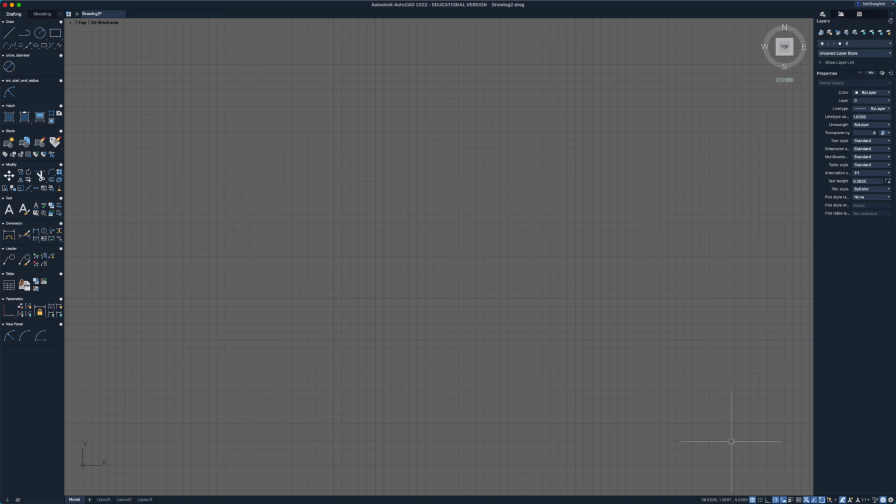So down at the bottom, this is where we're going to make most of our changes. As you can see, as I move my mouse, these numbers with decimals are changing. Those are the X, Y and Z coordinates. So if I move over near the UCS symbol down towards the origin, it should get closer and closer to 0, 0, 0. Okay, now beside that is a tab that is highlighted in blue right now with a bunch of lines going in a vertical and a bunch of lines going in a horizontal direction, and that is our grid.